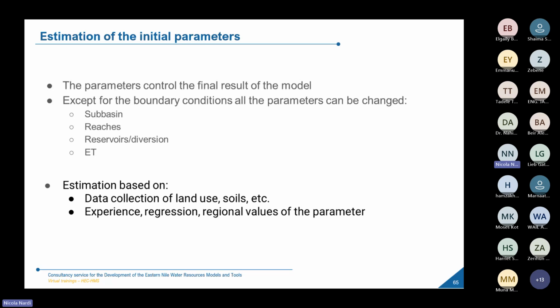And then if you have the possibility, it's always better to do a data collection, so some field survey, for example, for the infiltration, also in this case, the land use. What could be useful in this case would be a sort of infiltration test, and something that is useful to understand also the type of soil.